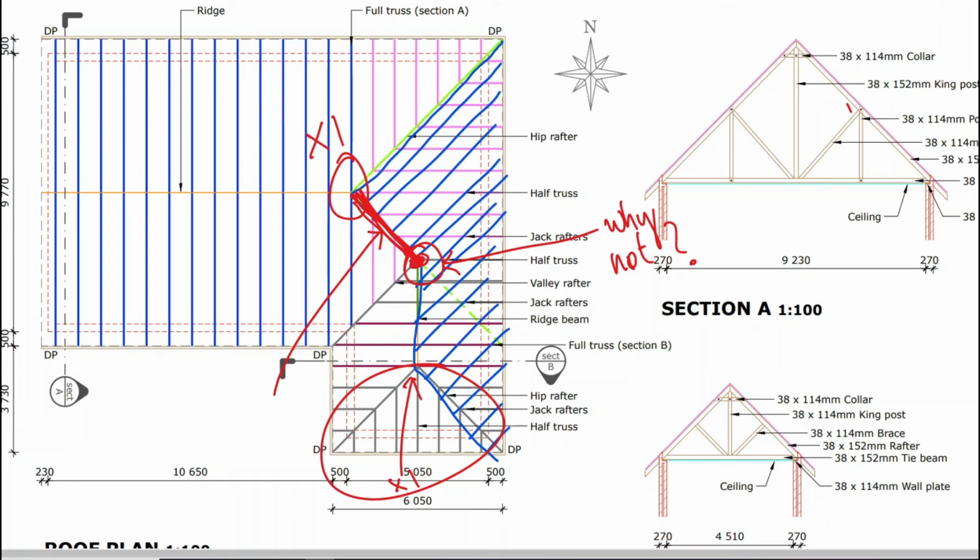And then we have a valley running this way. So valleys we ignore for obvious reasons. And then we have a ridge that continues. So all we have is a bunch of tiles sort of coming in this way. These are ridge tiles, by the way. I'm not sure if you can tell from my fantastic drawing, but it's changing angle slightly, and then it's sort of going this way. So our ridge tiles at this intersection do not need some sort of really elaborate purpose-made tile. I think they'll come up with a way of sort of waterproofing that and making it sealed.